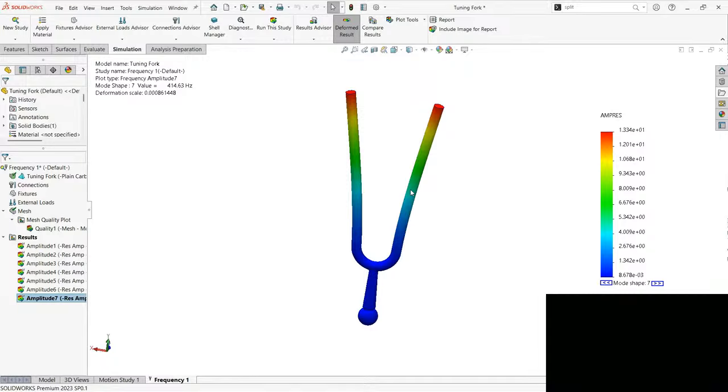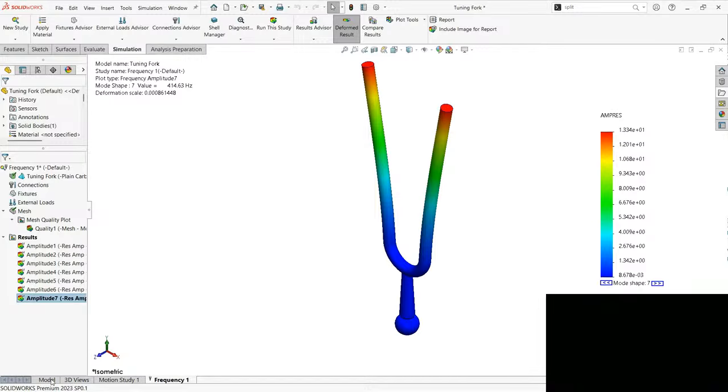Okay, the main thing of this modal analysis is to check the assembly and find out the resonant frequency and also the mode shape, how the component is behaving with respect to the stresses. If you have the stresses, there are a lot of modal analyses with the pre-stress included and the fixtures with also the load application. So there are a lot of applications available, but in this session this is what we have covered. I hope it is clear for each and everyone.